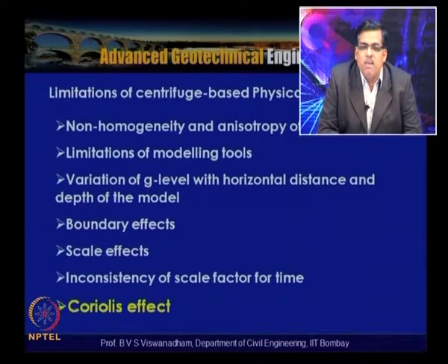And then the boundary effects. Models, especially of sandy soils, exhibit very severe boundary effects, which are nothing but the friction between the soil and the inner sides of the walls of the container.